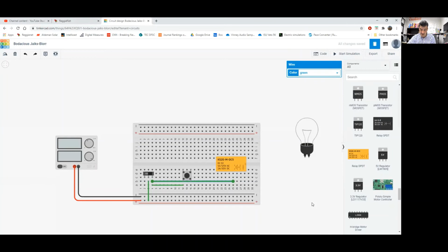That looks good. All right, so the next wire, I'm looking at my first rung still. I need to go from the output of the start push button to the coil. So I need to go from here, that's the output of the start push button, to the coil. The coil input is terminal 16. So I'm going to go to right there, and then I'll make this look a little bit prettier. I just like horizontal and vertical lines as much as possible.